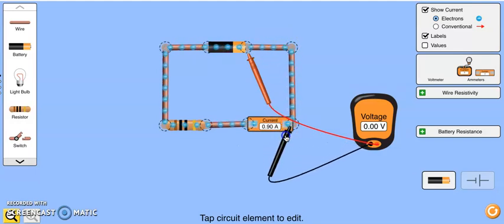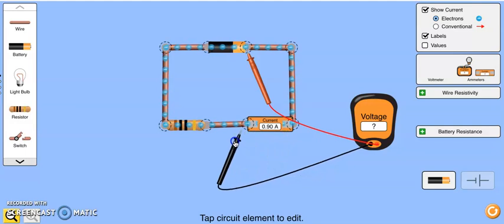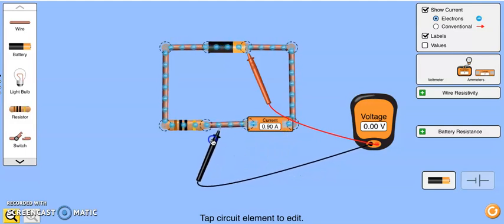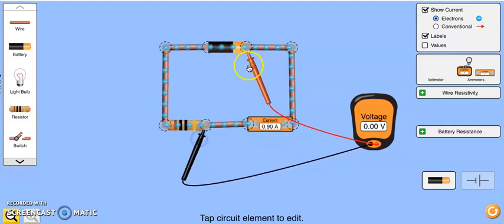And if I move the black lead here, still 0 volts. Now, is there going to be some difference when I get through the ammeter? Nothing. So from here to here, they're all at 9 volts. So think of a river where it's at the same altitude. Every part of here is at the same altitude, and it's a high altitude because it's a high potential.